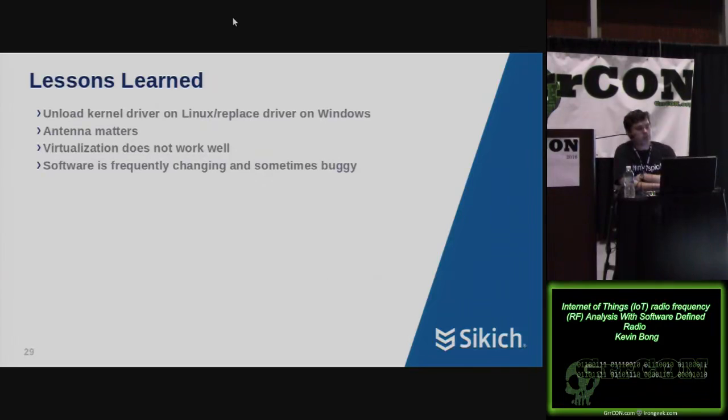Question was, would it be possible to utilize this with an RFID tag? So this dongle, no, because it doesn't get that low of a frequency. If you go out to AliExpress, you'll see these dongles for like $10. You'll also see about $30 devices that go down to 100 kilohertz, which should be able to do a 125 kilohertz RFID tag, or the high frequency like MIFARE RFID, the 13.56 megahertz, something like that. So you can do it with software-defined radio, not this one. Other questions?